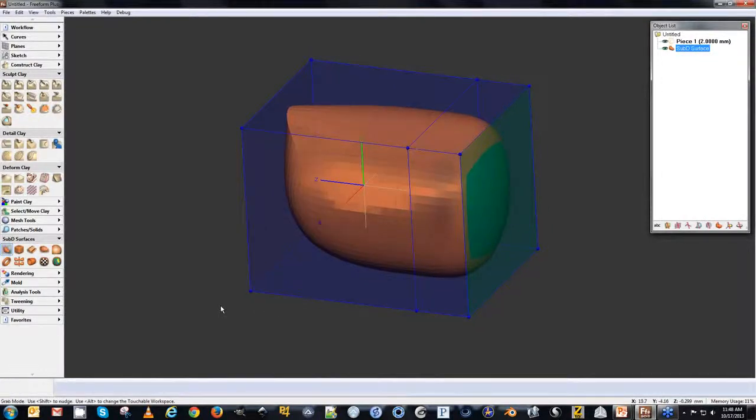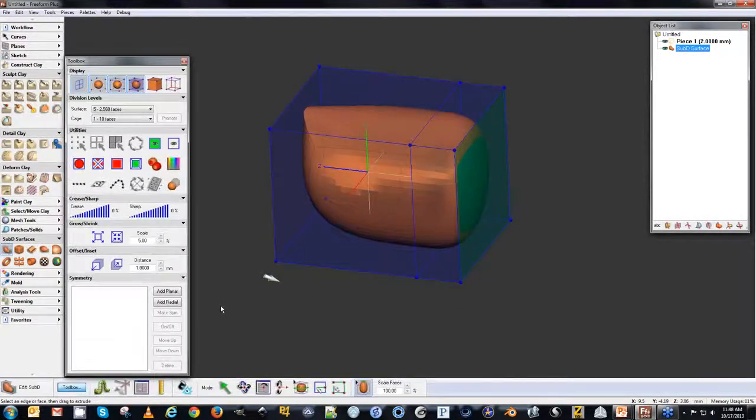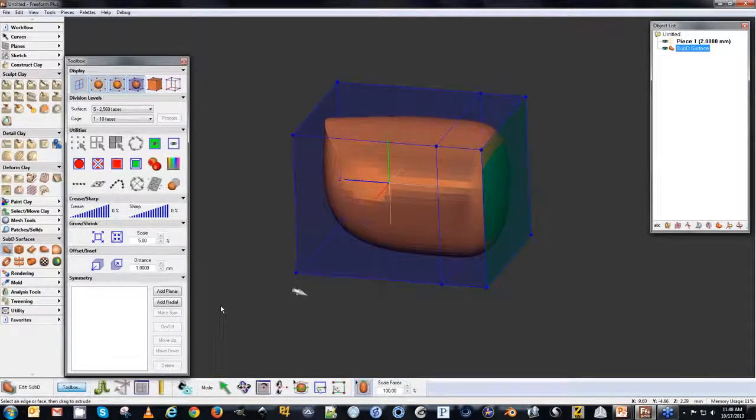Okay. Next question would be, modeling a leather handle is easier, but how would you approach a woven handle? The woven handle would probably take a lot more effort. I would end up cutting in the geometry the same way that I made the knife handle, where starting in the side view I would lay down certain points to define the individual strips, extrude them, and then add them back together. We also can add textures to this, which I didn't get into in this demonstration.